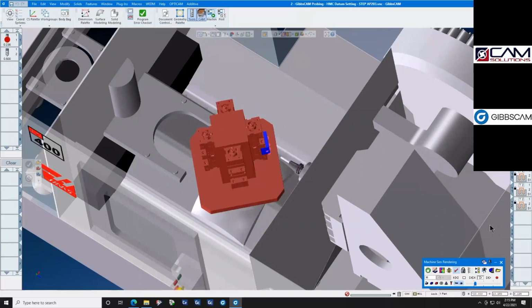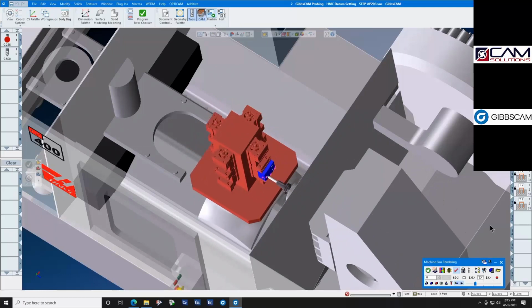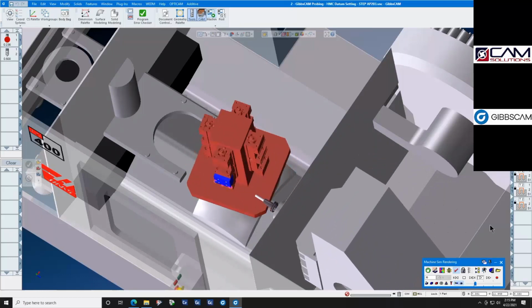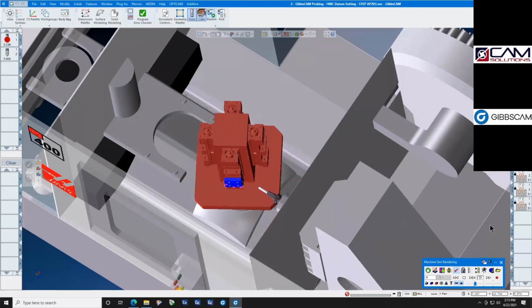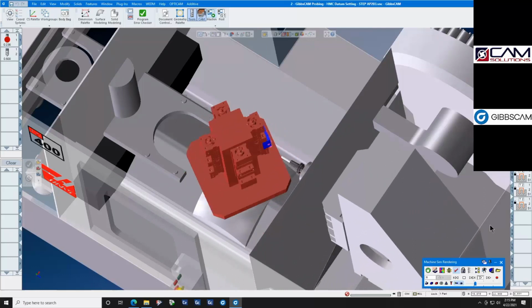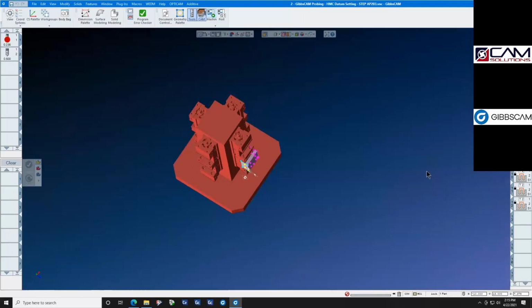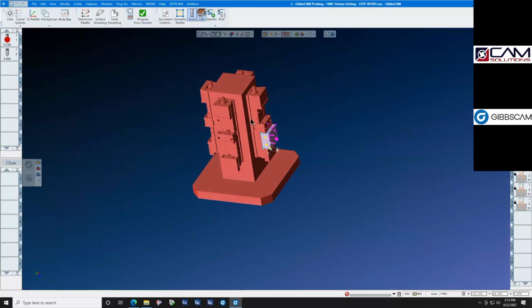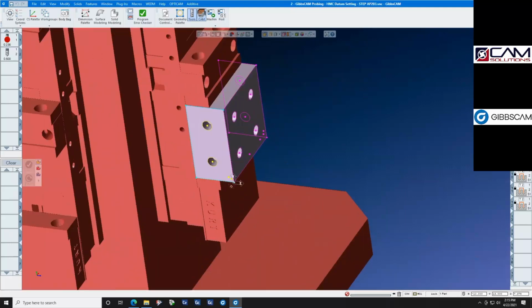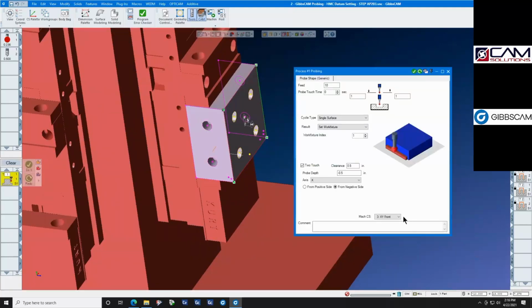If these were parts that were pre-machined in a previous operation, Op 10, and you loaded them into the vise here for Op 20, and you don't have room for a part stop, the operator simply puts the part in the vise, the probe finds it, locates it, and sets the datums automatically, reducing your setup time by as much as 90%. So what does an operation look like on a 4-axis machine? It looks exactly the same as it does on a 3-axis machine, except we have different coordinate systems.